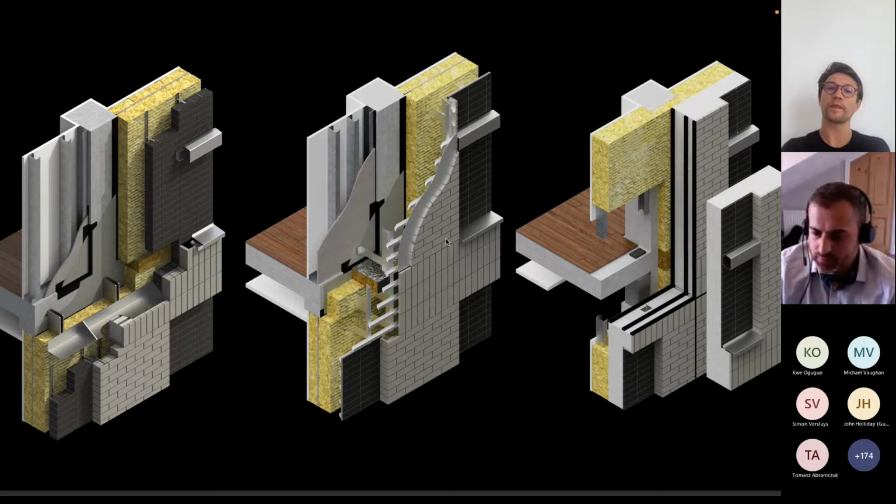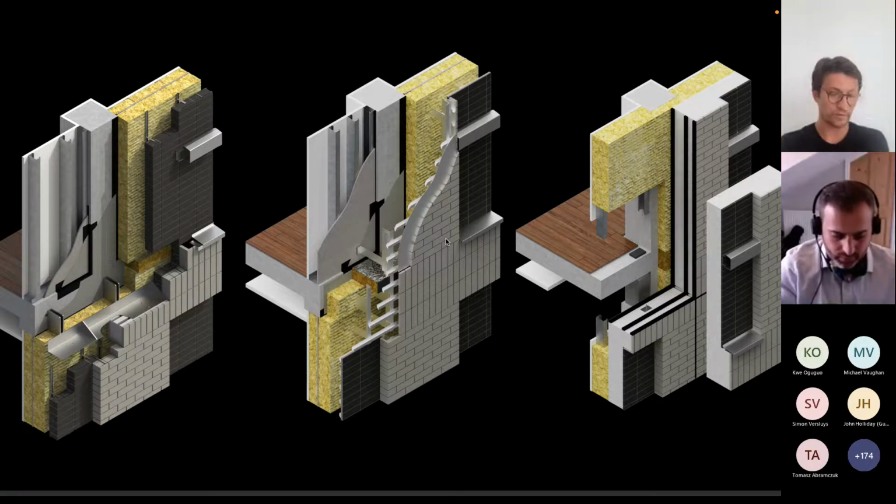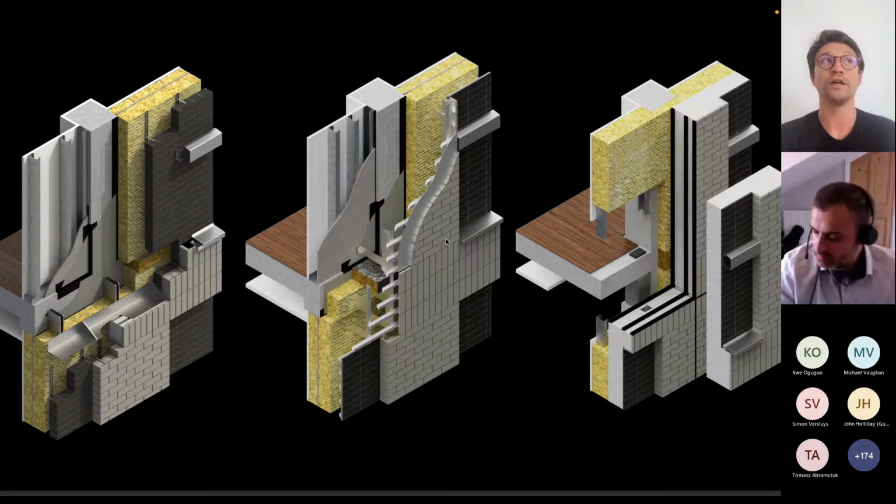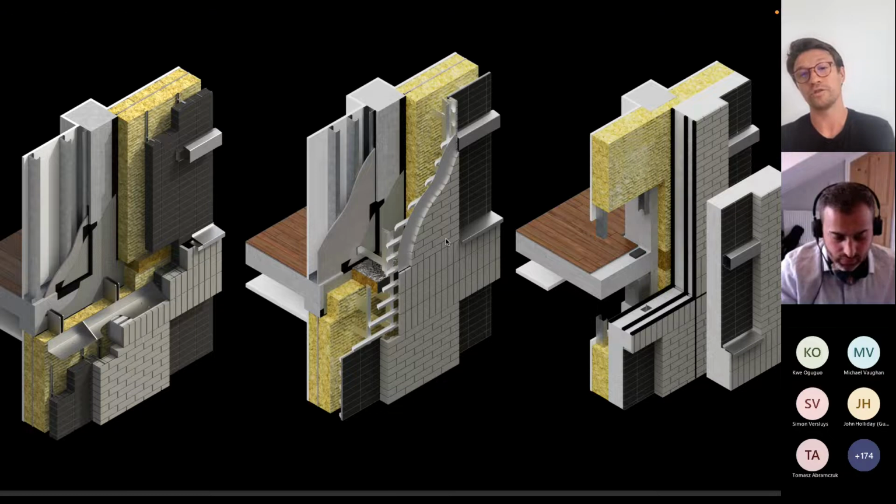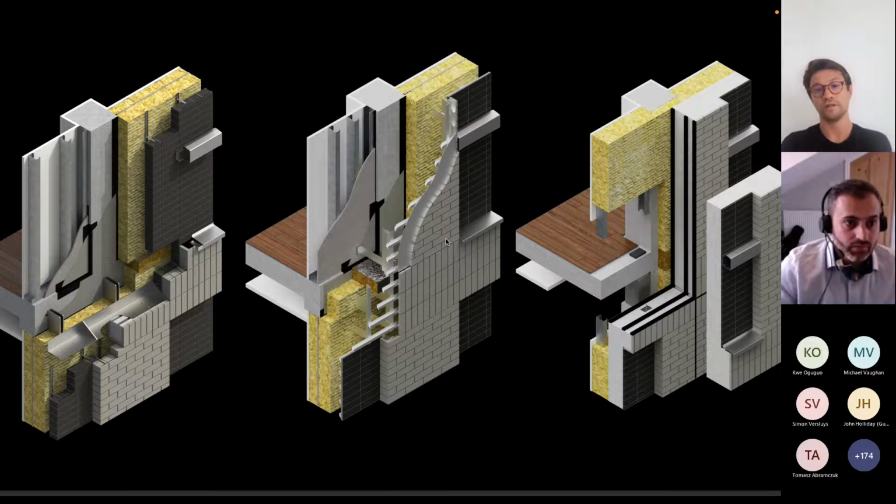I think it's a freeze-thaw test, when they take a cube of precast concrete and freeze and thaw it for X amount of time. Life cycle test, sorry, that's what it's called. So there's a British standard for precast concrete, and it covers any cast elements such as terracotta, stone, and brick slips cast into the precast, and it should cover you for most of the projects.